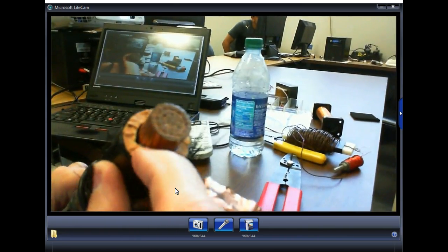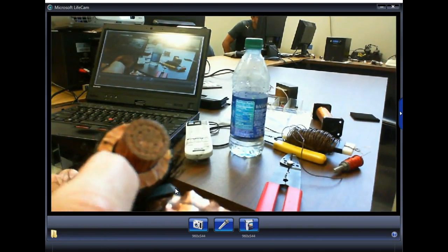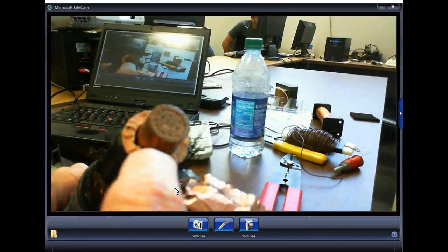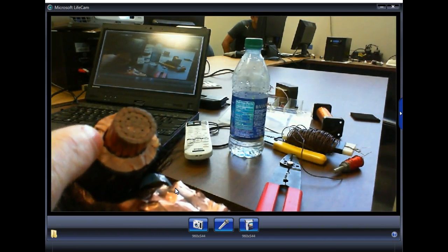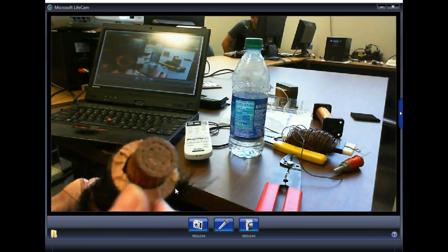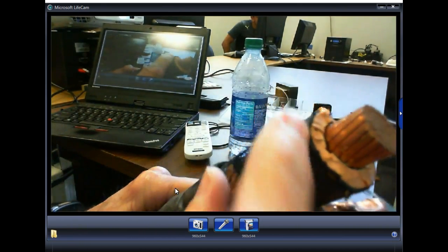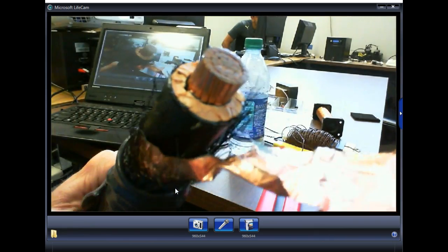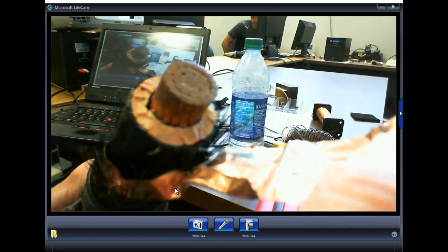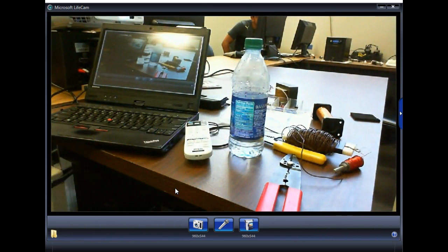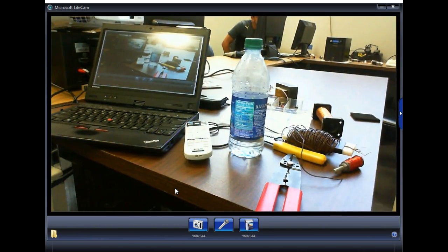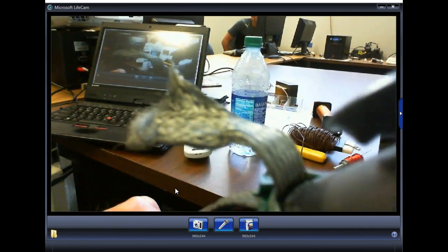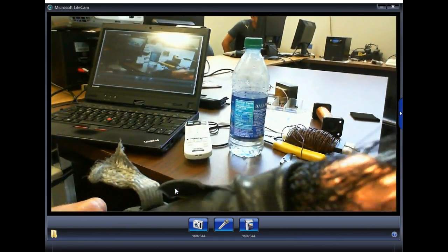This is the semiconductor layer. So when you pass this around, this is heavy. You see this black layer right here, right up against the conductor. There's the semiconductor layer. Here's the insulator. Here's the second semiconductor layer. Here is the what? Shield. We can't really see it, but this is the outside jacket. This is another layer, this mesh right here. I don't know if this is semiconductor or not, outside the shield.